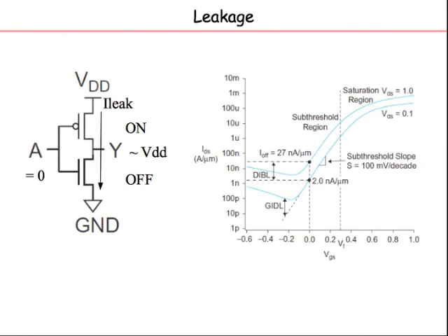In addition, we have another problem: I have a drain source voltage, but my gate source voltage is less than Vt, where we said the transistor is off. It's not really off, because you see there is still some channel formed. If there is some positive gate source voltage, it will attract some amount of carriers. So there will be some small amount of inversion, and you will still have a channel and some current. Before, you could ignore that current, as the overall currents in the system were much larger. But now, as we go forward, we can't ignore those currents. That is called sub-threshold leakage current.